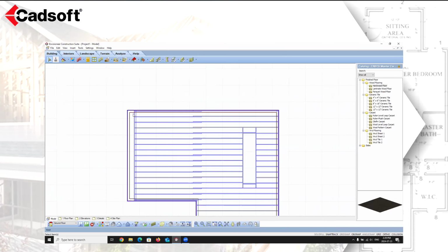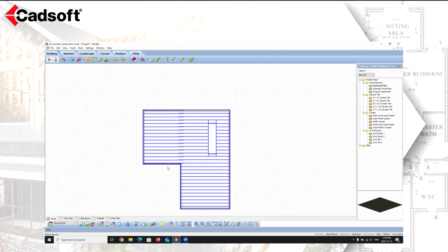So you want to make sure that you get the walls in stone before you start editing your floor framing. Again, I know changes happen in designs quite regularly, but again, you want to try and get it as close to being in concrete or in stone as to where the walls are going to sit before you start editing your floors and your openings. I'm just going to edit undo that to bring that wall back to where it was. And that covers everything that I wanted to show you in today's class in regards to floor framing.